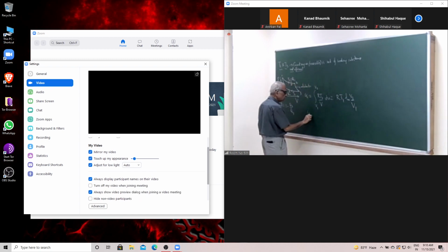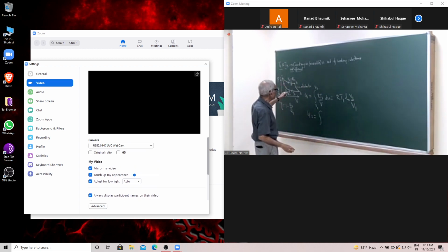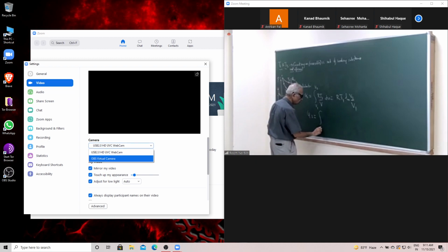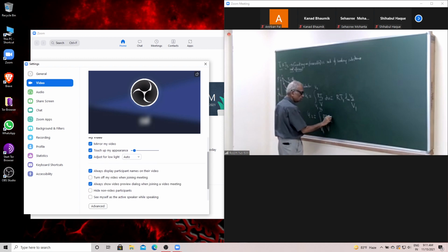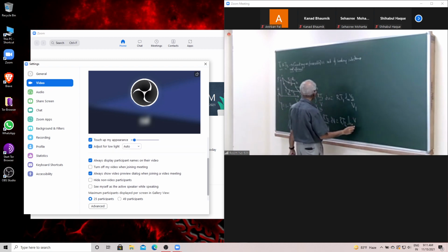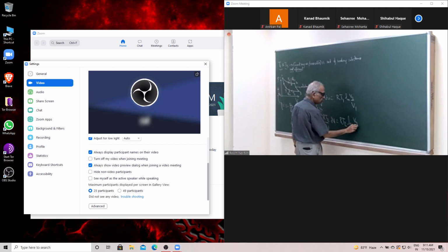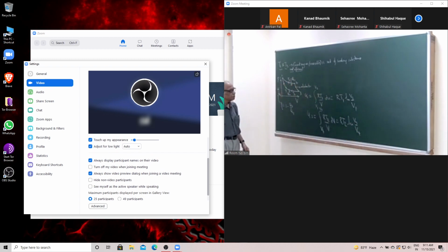And then there was Q2, the heat given out, whose magnitude is from V4 to V3, RT2 over V dV, which is equal to RT2 log of V3 by V4.